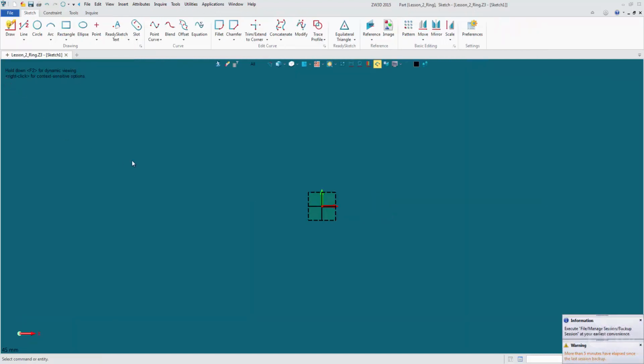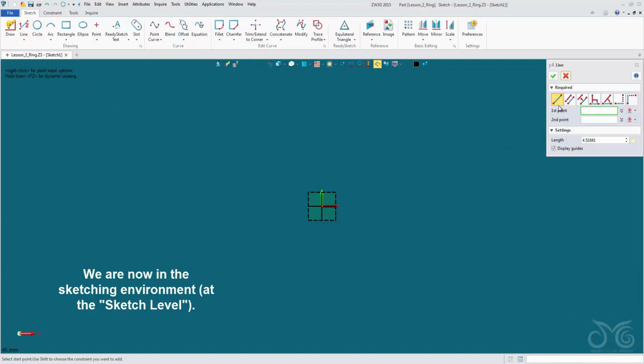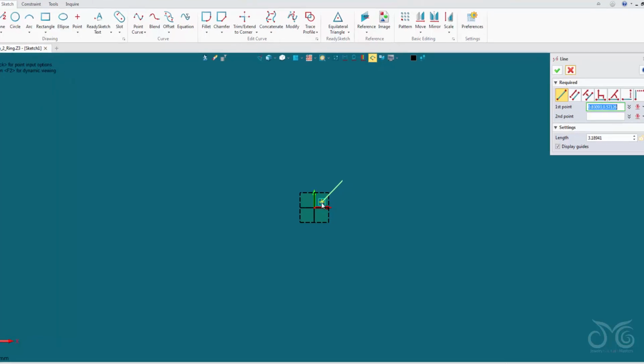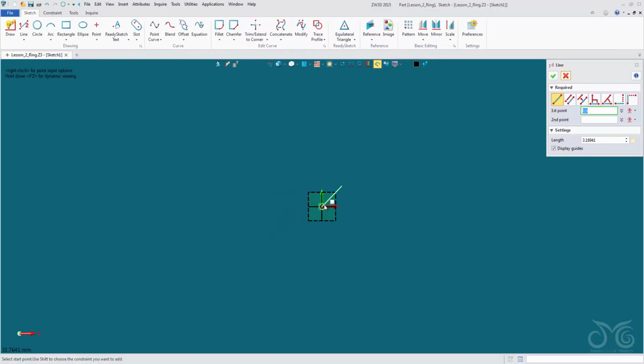Okay. Now I'm going to insert a line. I'm using a 2-point line. Now we left click to select the first point, and I want it right at the center here, at the origin. So I'm looking for it to come and snap in to the origin. Okay, we can see it snapped to the origin when there is this small yellow circle in here.